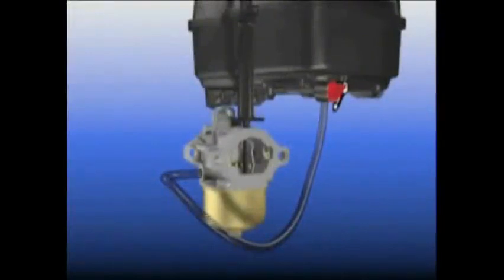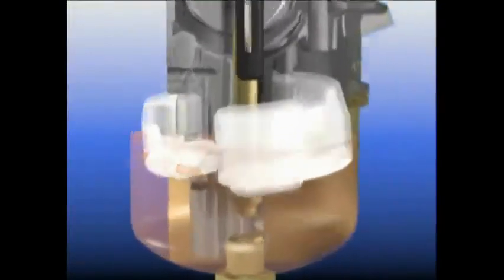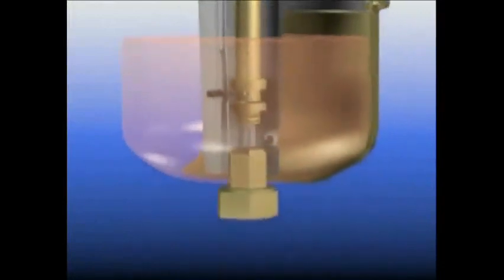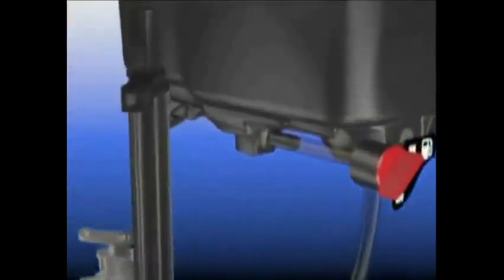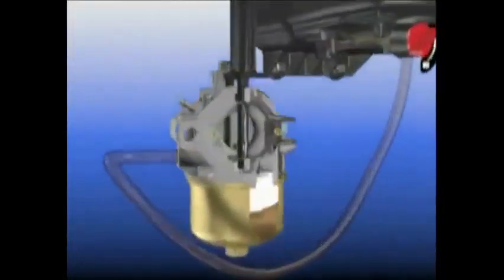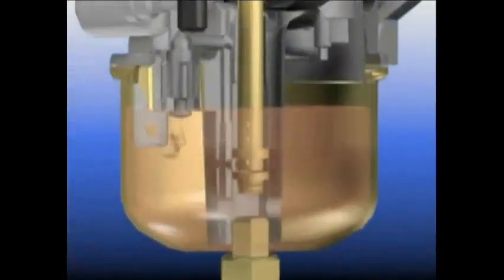If passing debris is smaller than the smallest orifice in the carburetor, it won't cause a problem, unless enough fine particulates pass through the fuel filter and coagulate in the carburetor passageways. Eventually, it could cause an obstruction, similar to an obstructed artery in the human heart. When the fuel filter becomes clogged with dirt, debris, or water, the flow of fuel will stop and not let the fuel through. If dirt or debris in the fuel manages to flow through the filter, it will end up in the carburetor bowl. If the dirt or debris lodges in the main jet, the fuel cannot flow up the high-speed circuit to start the engine.